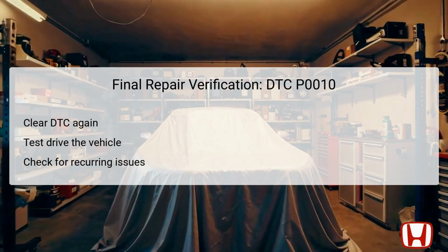Following this, a test drive of the vehicle is imperative to ensure that it operates correctly under various conditions, particularly paying attention to engine performance, idling smoothness, and response during acceleration. During the test drive, monitor for the recurrence of the check engine light and any abnormal symptoms that may arise. If the DTC remains absent after driving and the engine runs smoothly, it indicates successful repair. However, if the DTC reappears, further investigation will be needed to ascertain the problem's root cause.